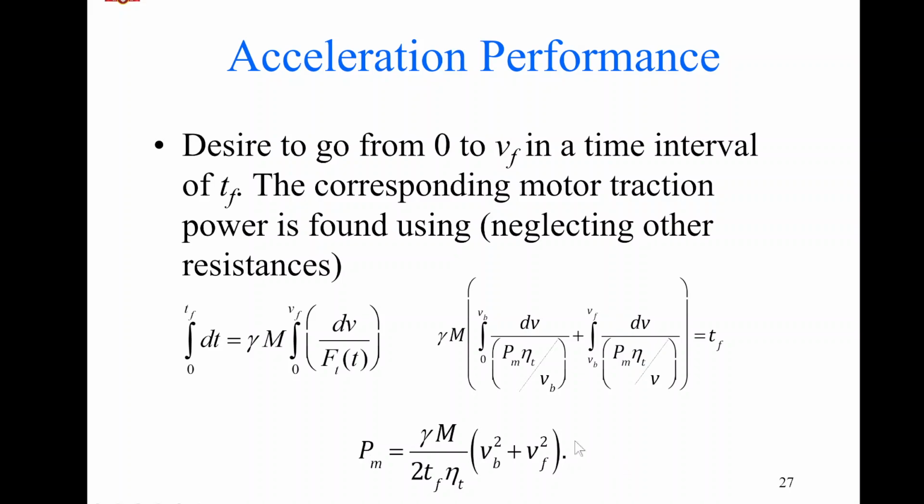we will end up getting this expression for the power. Here we are breaking down the integral into two parts: 0 to Vb, that is the time where we are linearly increasing the power as the vehicle speed increases, and from Vb to Vf, where we are looking at the constant power mode where the torque decreases.